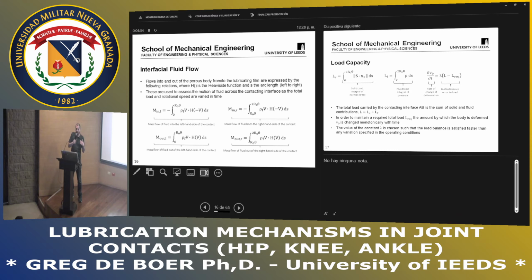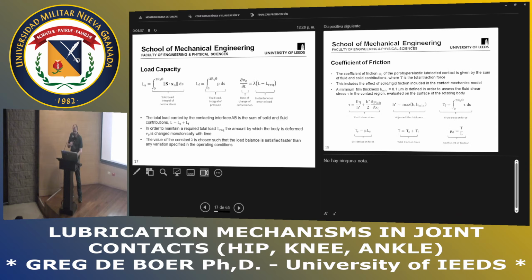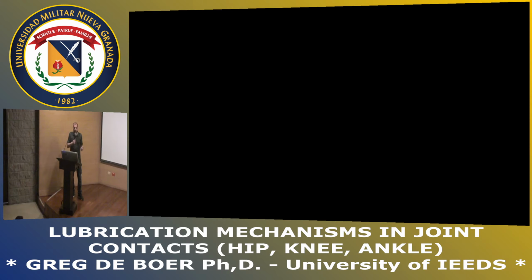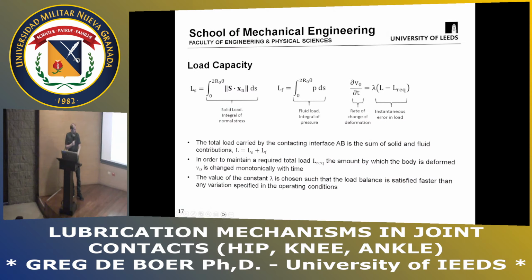Okay. We also have a load that's generated. So because the region is lubricated and in contact, we generate solid stresses and fluid pressures. And if I integrate those over that boundary, then I obtain the total load that they apply to the boundary. And that load needs to match to a certain value of the displacement, okay, which is the equation on the right-hand side.